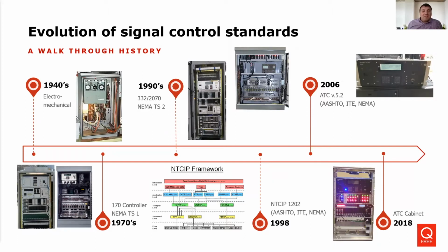In the 70s, we had a standardization, NEMA TS1, and that was a huge deal because it did 2 things. It governed similarities of operation of how the signal controller should operate in the field so that users are getting a consistent experience no matter where they are. The other thing it did is interoperability. So it governed the inputs and outputs, these 24-volt inputs and outputs, what each wire going in and out of the controller did. That means that theoretically, you could take any manufacturer that made a TS1 controller and put it in any TS1 standard cabinet, and you can intermix these things over time. Very basic standard, not a lot going on in terms of communications and things like that.